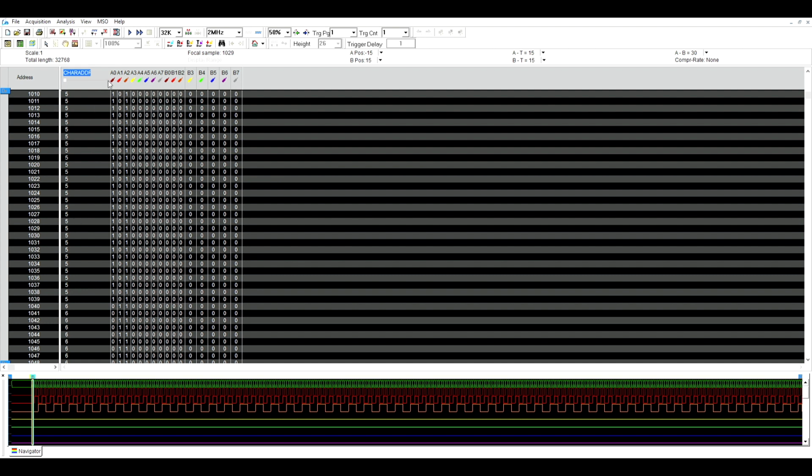So all you are seeing are the least significant bits, which are these 3 here in probe A0, A1, and A2. The other 8 are always 0, again, because we are not hooking this chip up to the video memory, so we don't get the base address or the address of the first byte of the character from the video memory. So this part I can't test, but it's so incredibly simple. We are just wiring the output of the video memory into these signals here, so not much can go wrong in there.